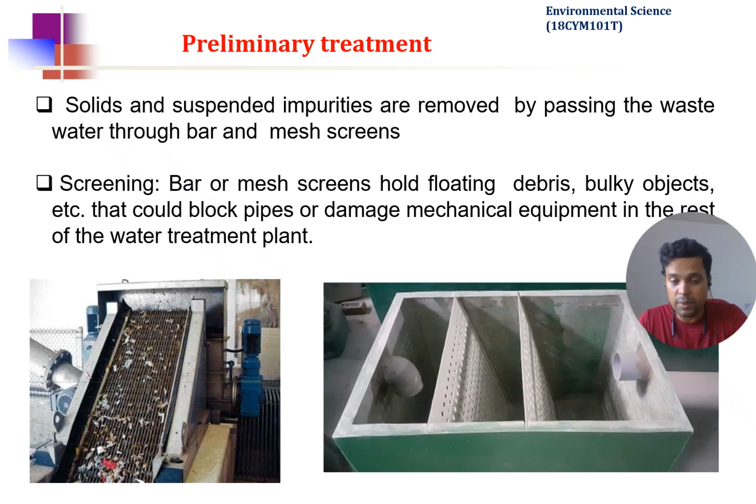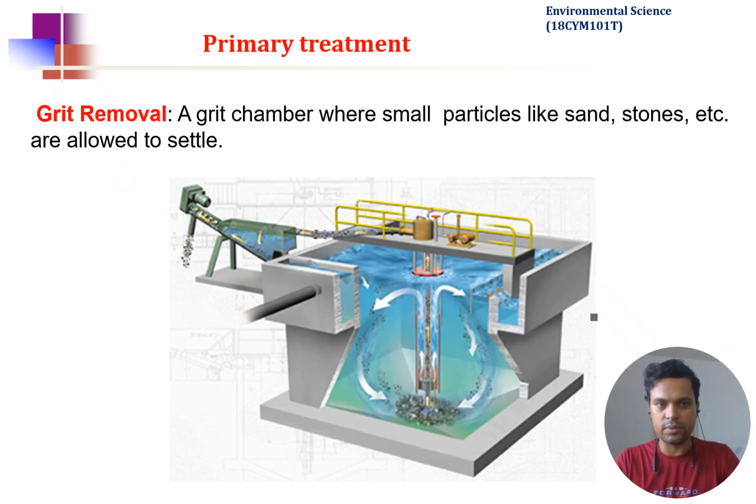And this is a very important step, because if you do not remove all these small particles, what will happen? In wastewater treatment there are a huge number of pumps present to push the water from one chamber to another chamber, and if particles are present in the water, they can damage the pump. So this is the major step to avoid any damage to the pump: the bars are placed in the water flow so that they can remove all the solid objects.